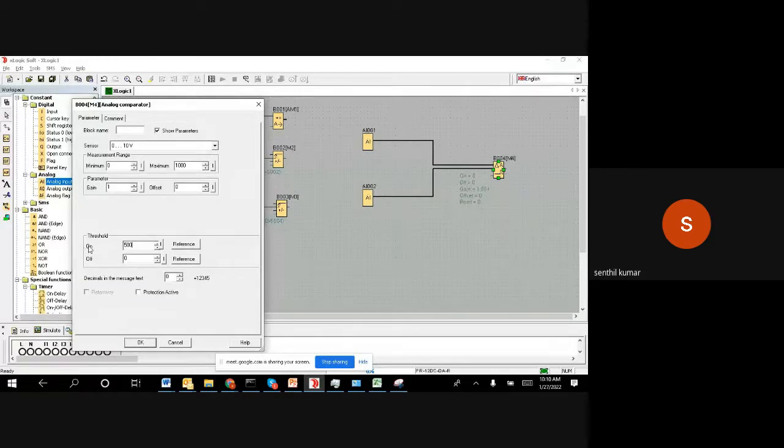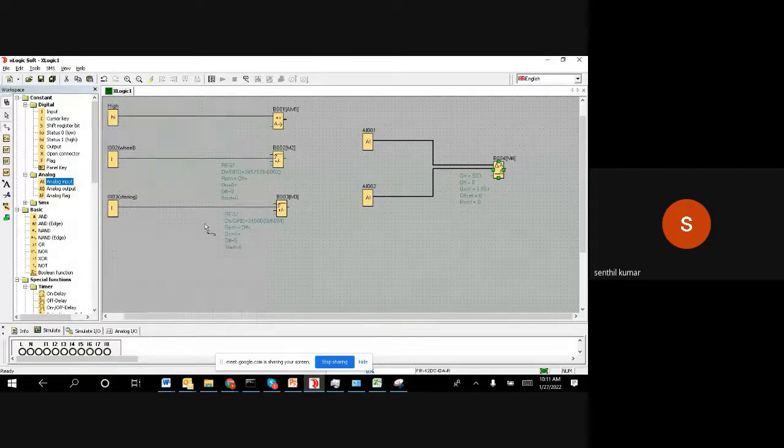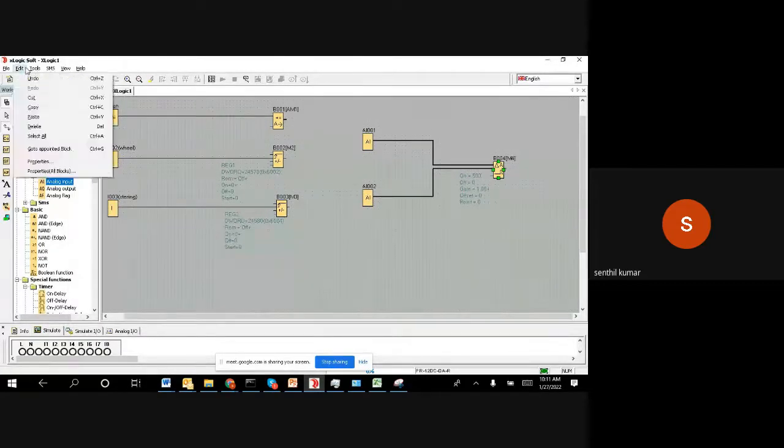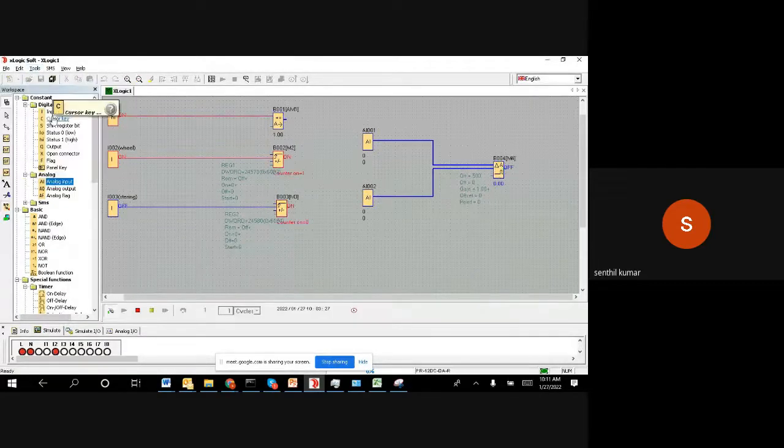On means we are saying when to switch on the output. So we are saying now when you compare AI1 and AI2, if AI1 is 500 more than AI002, then the output will become on. That's what it means. So we'll try to visualize, and then you get a better idea of my explanation, right?